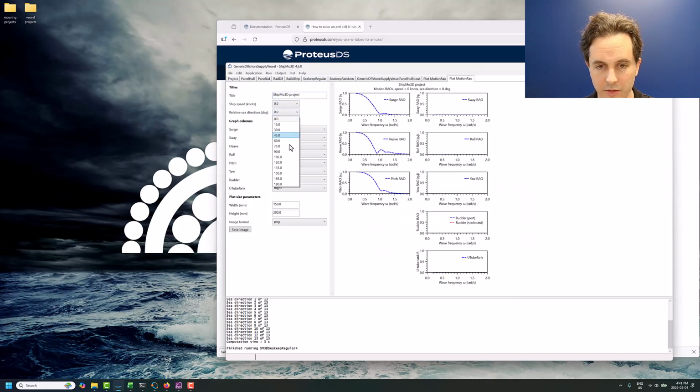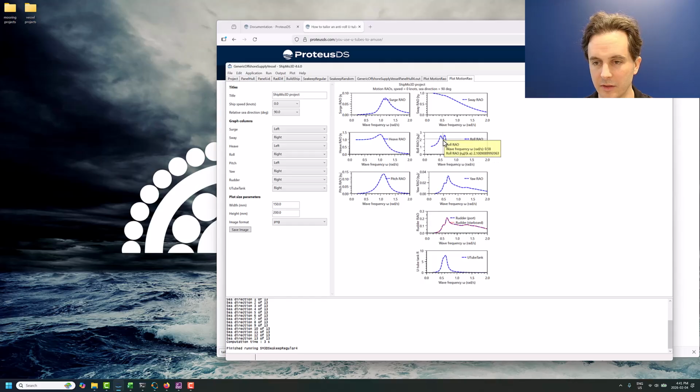Plot the motion RAO here. And there, okay, that looks nice. We've got sort of even sized peaks on either side here. Now at that same original natural period, it's gone down to 2. So 2 from 4, that's a 50% reduction. That's pretty good. It is a little bit higher on either side here, and then the U-tube, but that's what it's like with this kind of system. The U-tube tank frequency here is looking pretty well lined up.